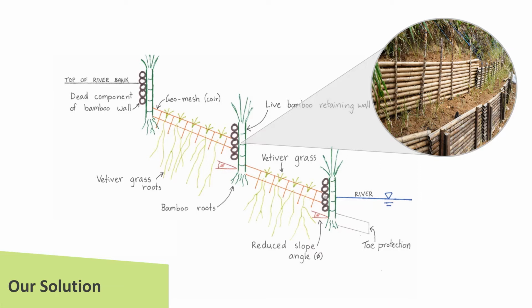We propose pushing soil down the slope to form terraces. The terraces will be retained by live bamboo cuttings dug deep into the slope. These provide support for bamboo to be stacked horizontally, forming the retaining wall.